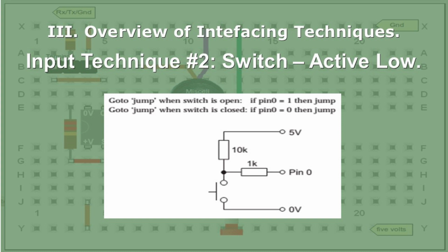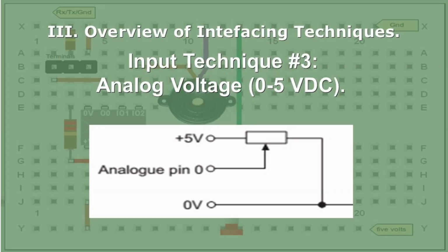And again, same problem. If you push that switch and it needs input, it's probably going to input about 100 times. And now I'm going to illustrate why. I'll talk about that in a few moments. The problem is that switch must be debounced. If you don't put debouncing in there, it will read that switch 100 times, and I'll show this later in the program.